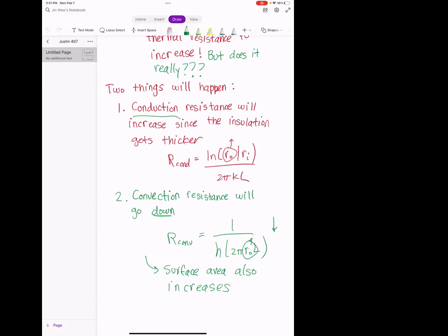We're solving for Q, but in this problem I actually give you the Q, so it's a bit of a mix up. On other problems you also had different added Qs, for example the film problem we did, where you added the Q of the air plus the Q of the substrate. We don't have a substrate in this problem, so we just rely on the Q that you gave us. The in-class example is interesting because the Q is inserted at the middle. Here the Q comes from this side, so the heat is going this way and you don't have to worry about any splitting. There's just going to be one Q.